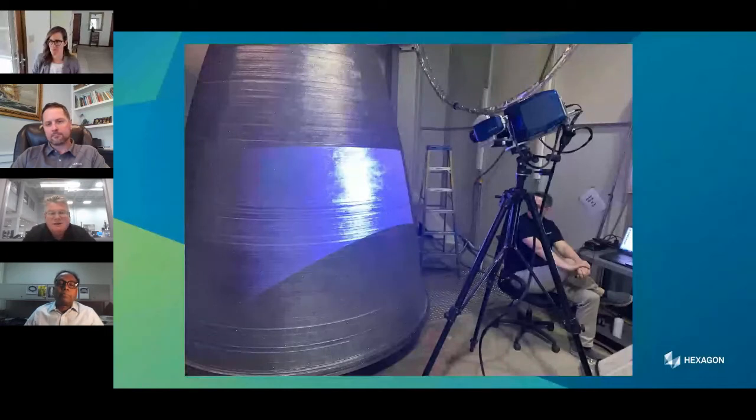And so there's no answer to the question which people may be asking, what's the right measurement device for my process? And that all depends on, or mostly depends on the size of the part and the accuracy that you require, and whether you need data for absolutely everything, including the insides, which means you maybe have to go to CT scanning.